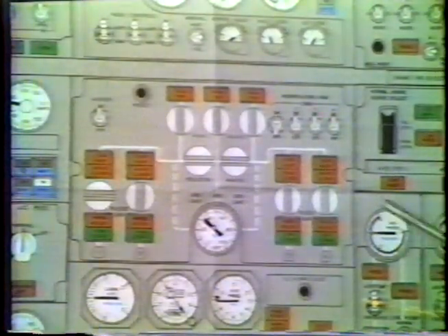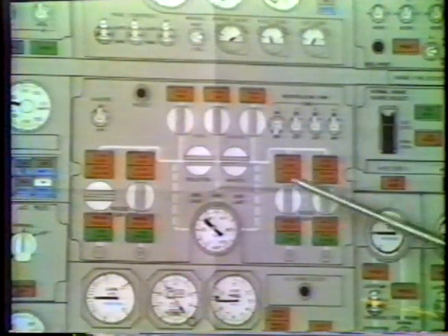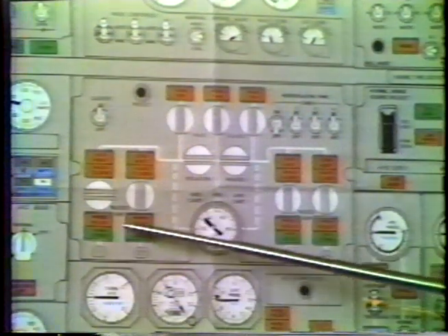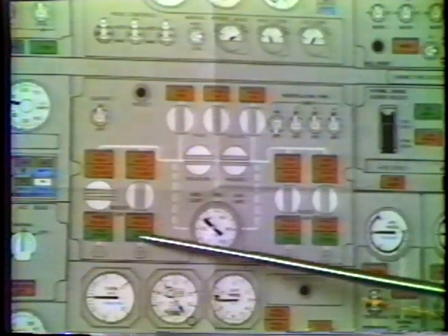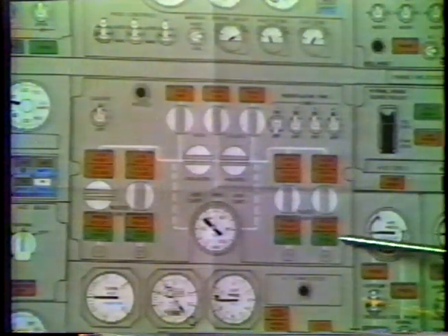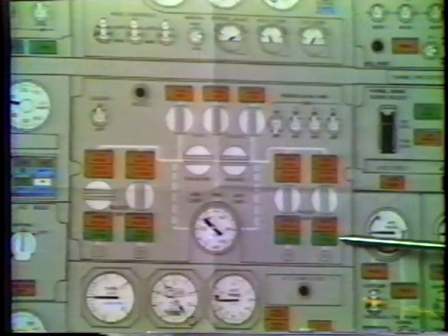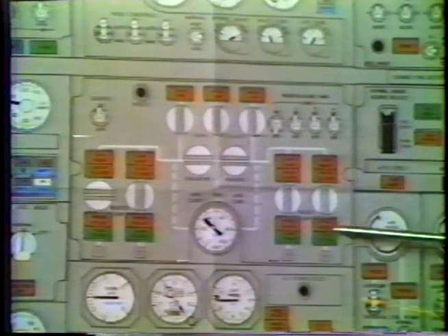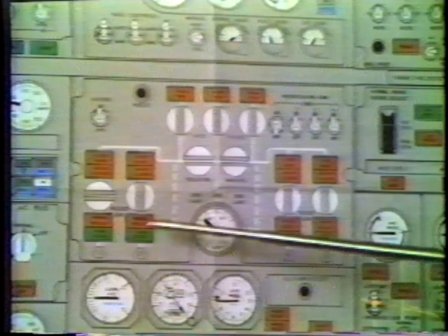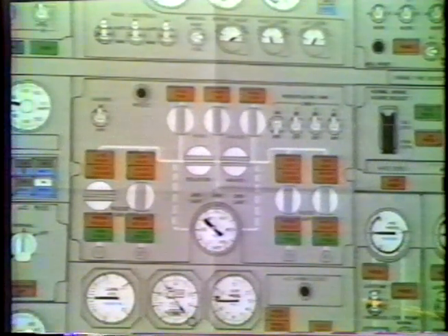A couple other things I'd like to point out on the pressurization pneumatic panel is the high stage light, which indicates that both high and low stage is being supplied to the pneumatic system. This can vary for various aircraft, but generally it happens at the lower altitudes around 77% N2.